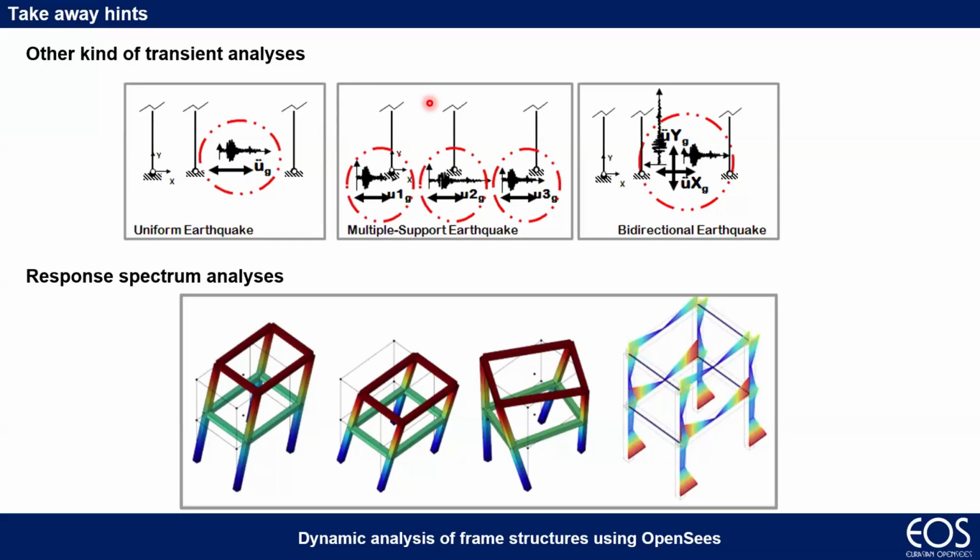Should I apply it on each pile node or on a particular node at the bottom of the pile? Are you getting my point? Like if I have 5 piles, each pile has 20 divisions, like 20-meter depth, then how should I apply the excitation force into the structure, onto the pile foundation? In general, the idea is it will come from the ground and go up. So if I have 5 piles, not a single line, how should I apply uniform excitation force?